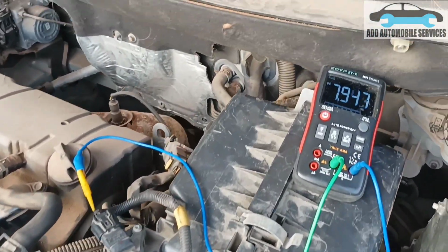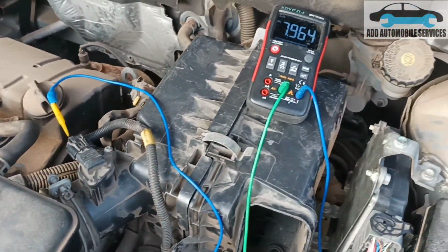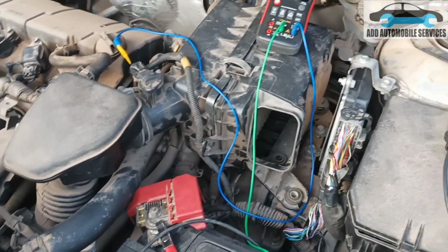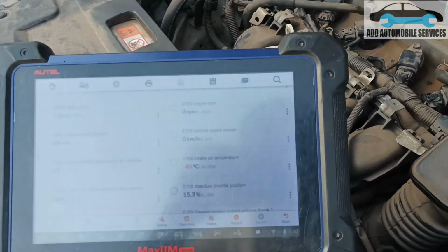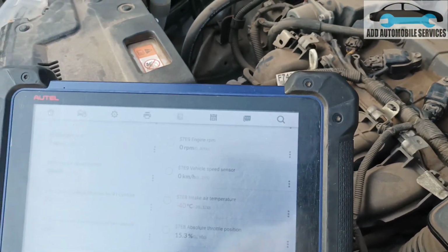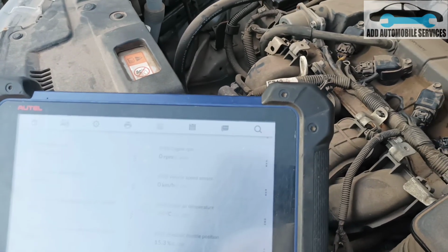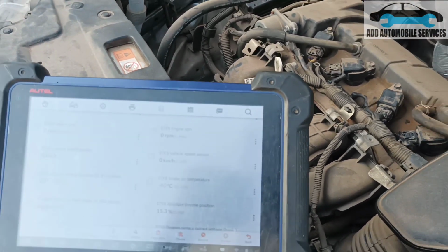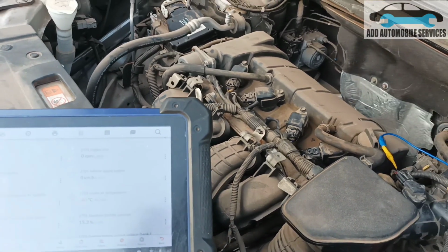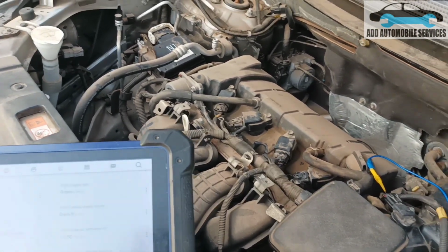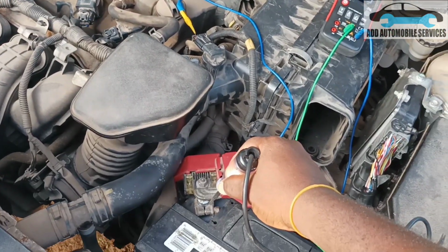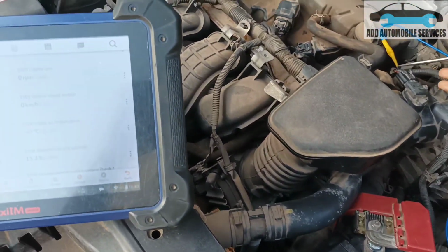So now the moment I plug it in, you can see I'm getting some voltages, which I don't think should come. I'm still having negative. So let me test it and see if I feed it with ground, will my test light change? And you can see the connection that I'm doing here. So let me try it and see.